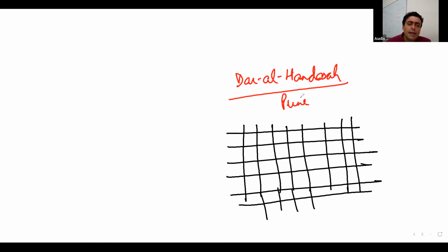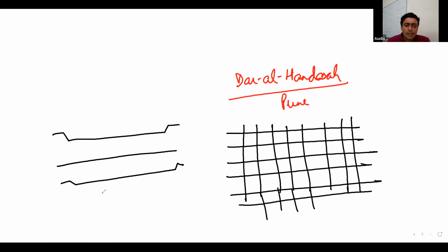Okay. In India, how do we provide reinforcements in slab? Generally, we would be providing bent-up bars, isn't it? Why do we provide bent-up bars? To achieve optimum designs. So we try to provide reinforcements where it is required.